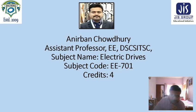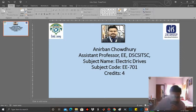That is the first quadrant, that is forward motoring. The second quadrant, it is the forward braking. Third quadrant, reverse motoring, and the fourth quadrant, reverse braking. Now this is applicable to all the drives, but in case of DC motor drives we are going to explore the speed torque plane, and we will study each of the operations, how they work, the different modes of connection that we are going to study. So let us proceed.